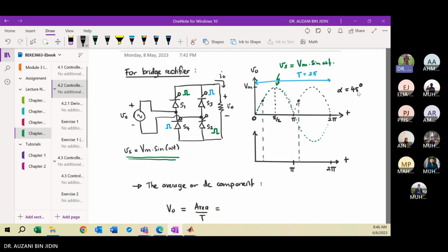So for the bottom graph here, this is the I pulse. From 0 here, you inject the current pulse here. This current pulse is for S1 and S2. You must turn on in pairs, S1 and S2. S1 and S2 receive the same current pulse, the green color, at the same angle, 45 degrees. I just write it in degrees.